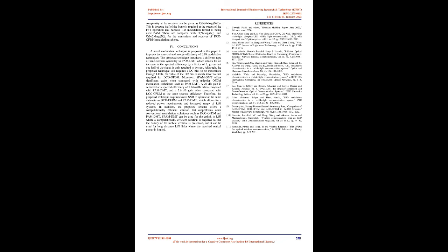10. The performance of 2 PAM-DMT is compared with the performance of 4 PAM-DMT and 4 QAM DCO-OFDM at a spectral efficiency of 1 bit/s/Hz in Fig. 6. It is shown that 2 PAM-DMT outperforms both 4 PAM-DMT and 4 QAM DCO-OFDM by 2.75 dB and 3 dB, respectively, at a BER of 10 to the power of minus 4.